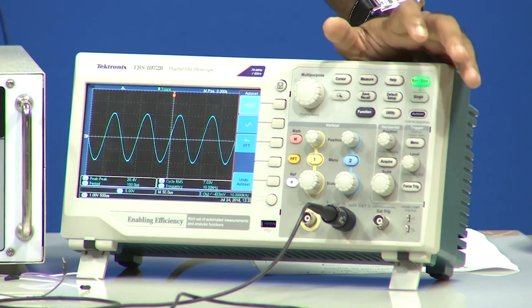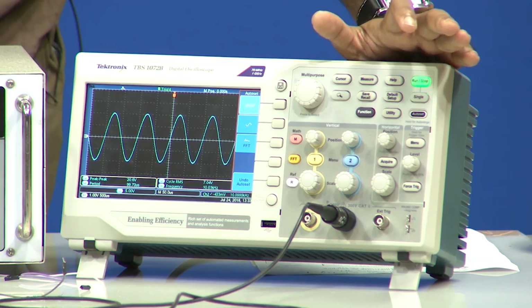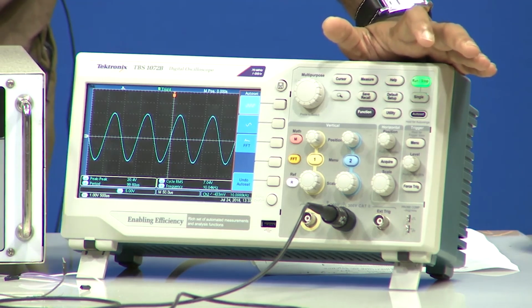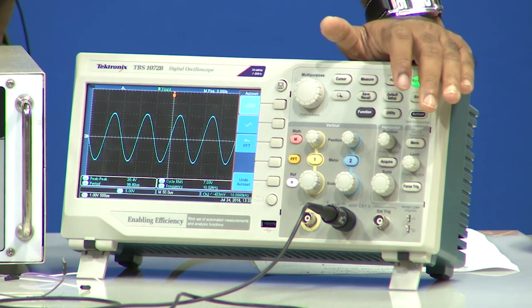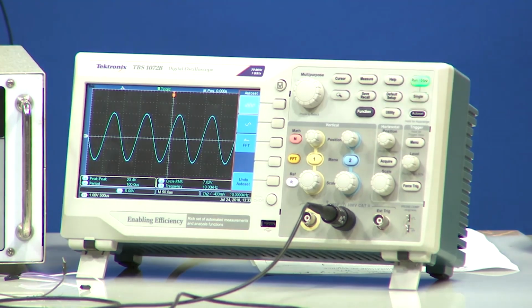This is the maximum that the function generator can provide. We have given almost 20 volt peak to peak input, and we are getting 20.4 volt output. The input is still faithfully reproduced. The range will go on if you are able to supply more voltage. So, when does the op amp saturate? When its single excursion goes to 13.4 volt, or the peak to peak voltage goes to around 26 or 27 volt. When we give around 26 volt input, we will get 26.4 to 27 volt output.